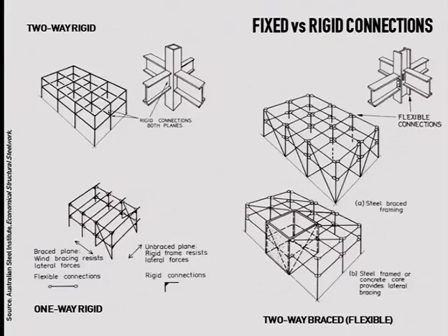And now I think we spoke about this slippage, and we need to mention that we can actually make two different types of connections. We can make several types of connections, but a main, very rough difference is between rigid and flexible. So rigid is a node that is able to transfer all the forces between elements. So what happens? We transfer compression, tension forces, we transfer bending moment. Flexible joints generally do not transfer bending moments in an appropriate way.